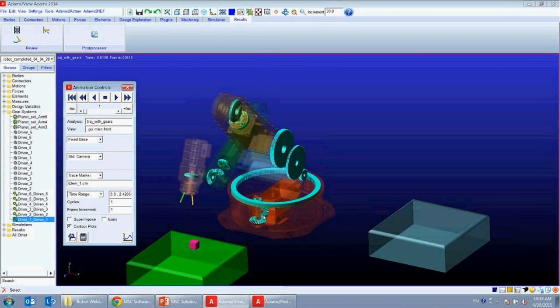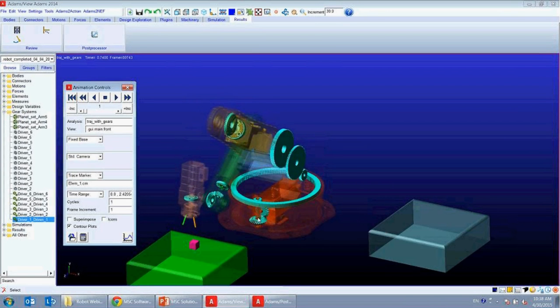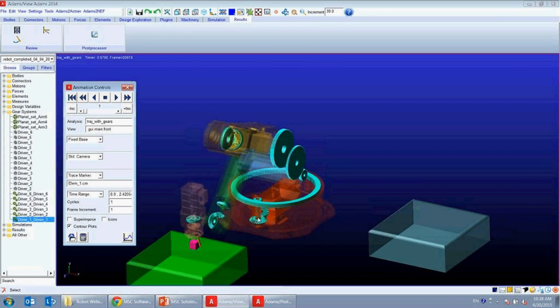So we did two simulations, the one with two gear pairs having some certain level of gear backlash. Another simulation is with the system going without any kind of backlash in any of the gear pairs. And then we actually compared the results for both simulations, and we observed some differences in the movement, in the XYZ displacement for this final object, which I will show you later in the post-processor.